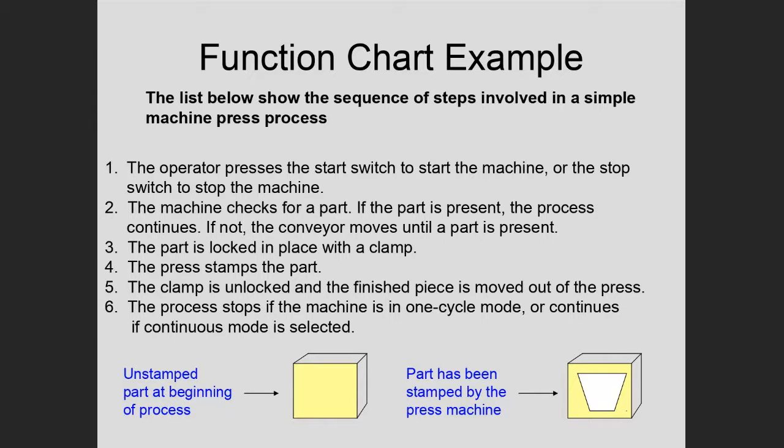So notice now, if you're actually going to program a PLC to do this process, somebody might describe it to you in words, or they might actually write out in a paragraph how the process should work. And you, as a PLC programmer, would have to translate the English to and/or logic and put it in the PLC the right way to get the correct functionality. But notice here we divided the whole process into these steps, and it turned out to be 6.